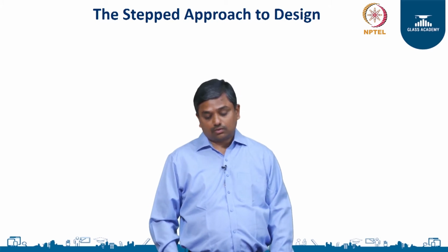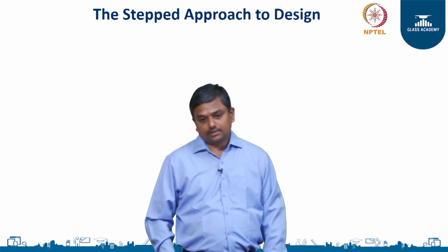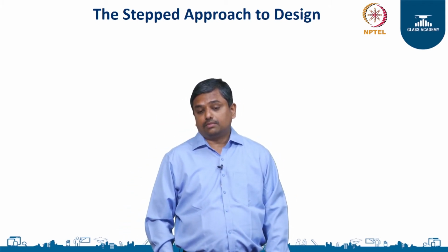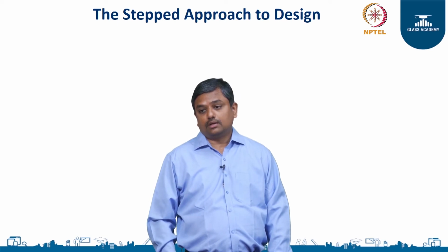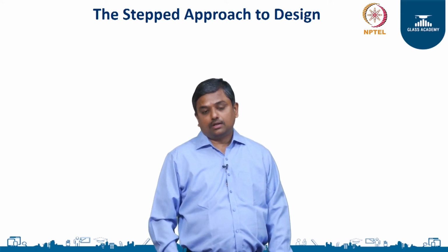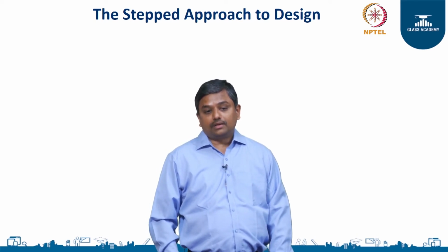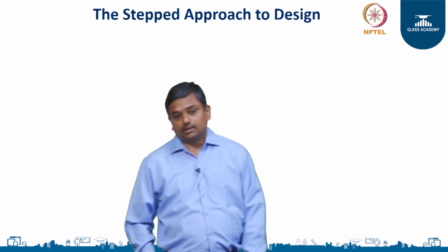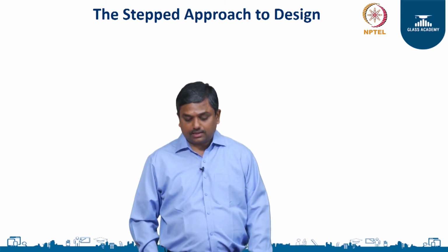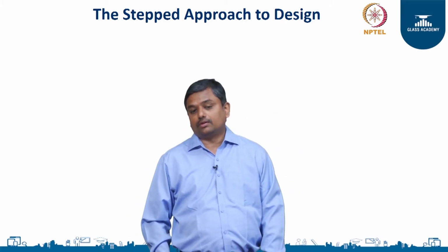In fact, there are requirements around commissioning of building envelopes today, which have been introduced in rating systems, where third-party commissioning agents actually come and verify the building envelope and test it and certify it, to ensure that the properties that have been committed by the manufacturer are actually on the site. So, it is gaining a lot of importance, and the envelope is very important in terms of achieving building performance